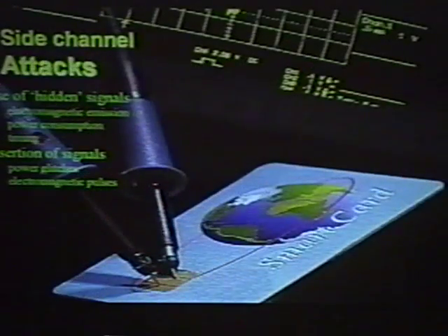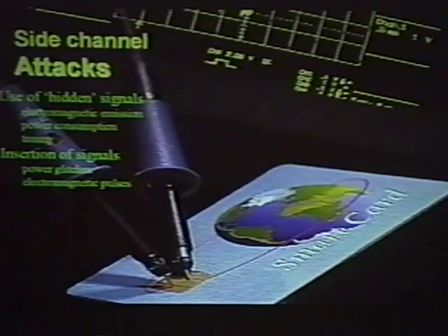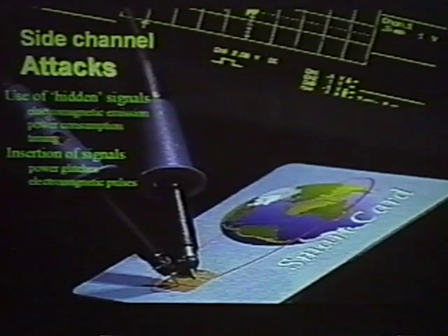It's all pretty straightforward. I'm getting to the last class of attacks, the side channel attacks. This class of attacks got popular about 4 years ago, and it appears to be very powerful, and the problems that have arisen are far from over right now, although manufacturers are working quite hard. This is what it's all about. The smart card has one single pin for normal communication, but unintended, it communicates in another way as well. It transmits electronic emission about what it's doing. It uses power, it has some power consumption.